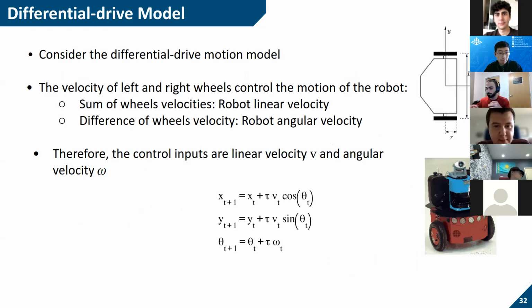So you can think of a robot that has full control over both left and right wheel velocities, and based on that it can adjust its linear velocity and angular velocity. Yeah, exactly. DC or stepper motors are practical implementations for differential drive. Basically you need two motors, or a differential with one motor, in order to mimic this functionality.